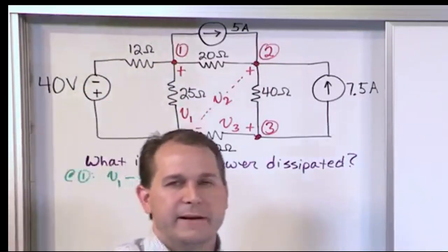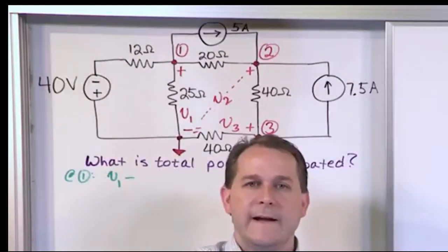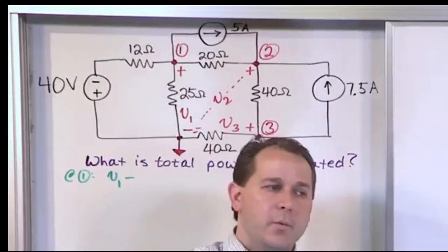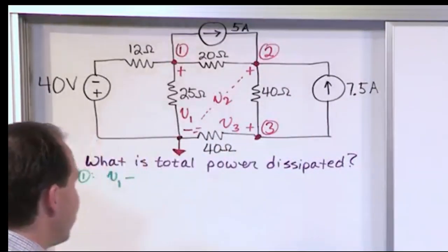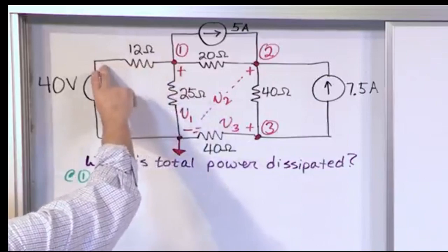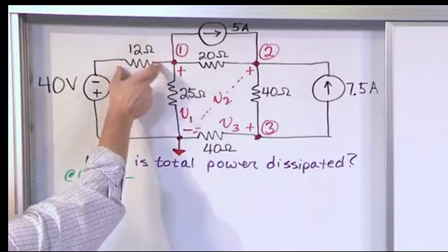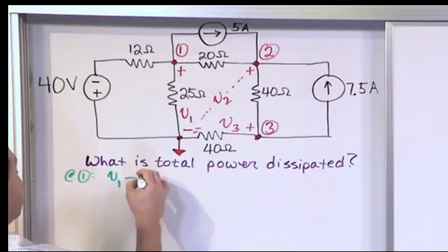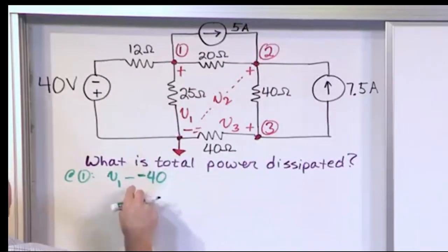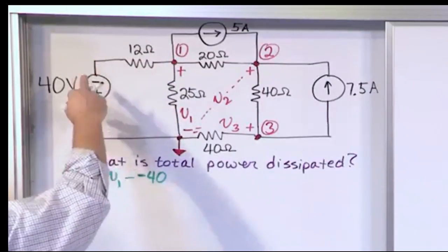And that makes sense because if you have a 12 ohm resistor and you have a voltage on one side and a voltage on the other side, if you subtract the voltages, then what you're getting is the voltage drop across that resistor. That is perfectly fine to do whenever this is plus minus, because you're popping up here, subtracting off some other voltage, that gives you the drop. The only difference here is that we've reversed this. So you're still subtracting, but you have to subtract a negative 40. So it's a minus because we're subtracting the voltages, but it's minus 40 because I've flipped it around.